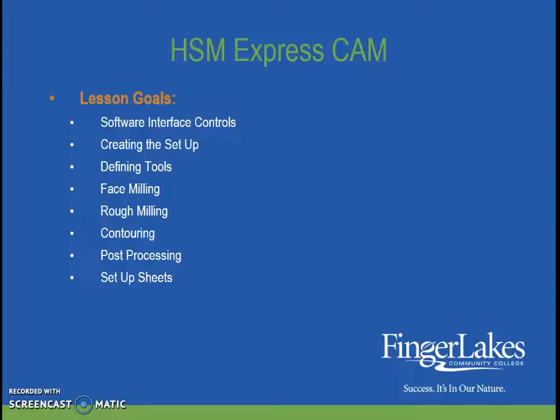The goals of this lesson are to understand the software interface controls, understand how to create the setup of the part in HSM, and define the tools that you're actually going to cut with. Then we'll talk about face milling, rough milling, contouring, post-processing, and something you'll like, for those of you who remember creating by hand the setup sheets as the process plan. This will create those setup sheets for you in HSM Express.